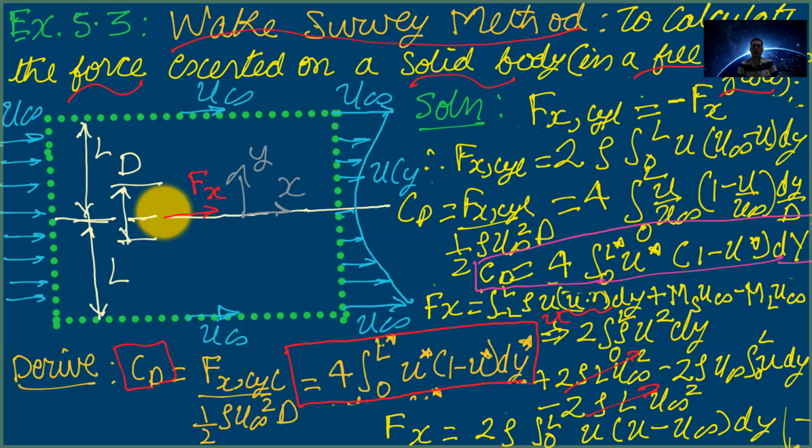So while applying momentum conservation, be conscious enough to make sure that the mass conservation is obeyed, even if it is not explicitly stated in a problem. For most of the momentum conservation problems, this is not stated. But you should be clever enough to judge and calculate the mass flow rates in certain boundaries where it is not given. Otherwise, you will miss the momentum transfer on that boundary and you can get into wrong solutions.